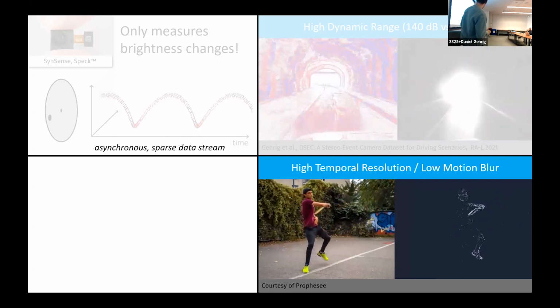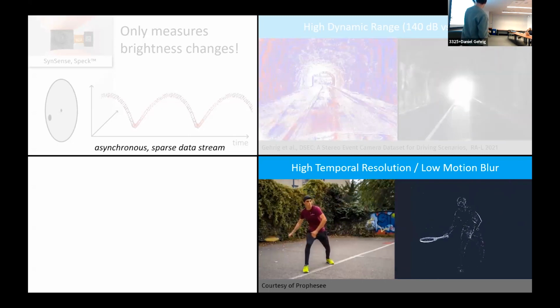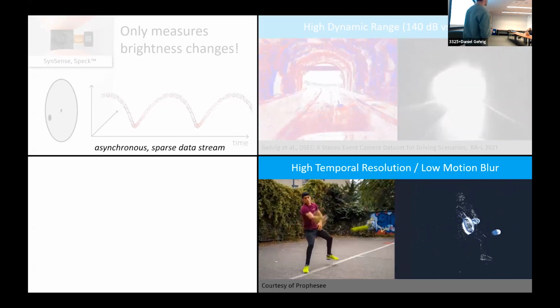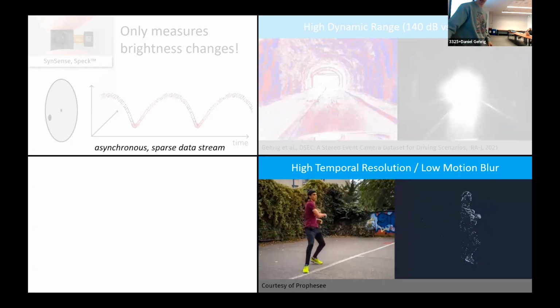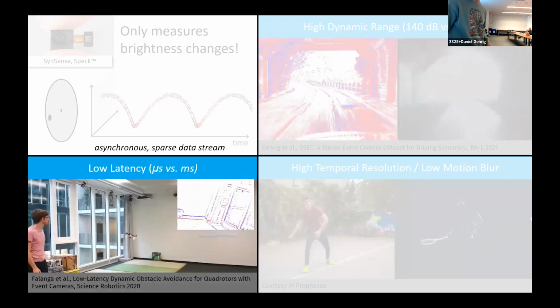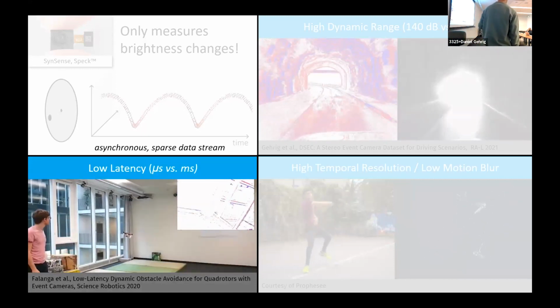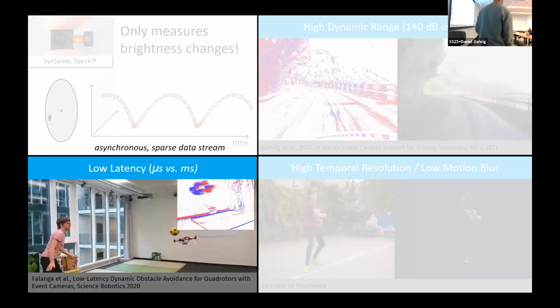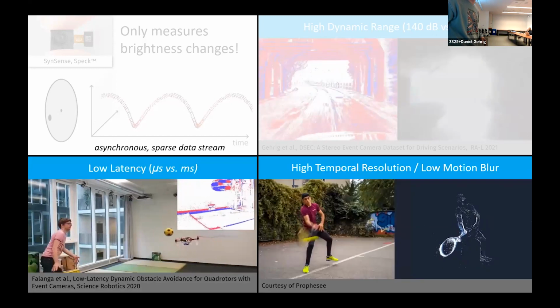By contrast, the standard camera has motion blur, especially for example at time of impact with the ball, which is maybe a very important event in robotics application. We have a very high motion blur artifact. Finally, here we see that event cameras also feature a low perceptual latency. This makes them especially interesting for these kind of high-speed maneuvers that we would like to do with robotics.